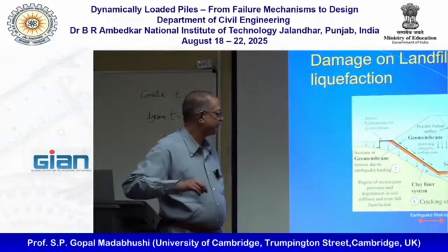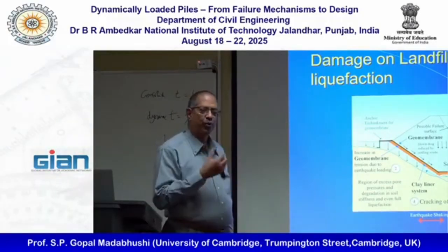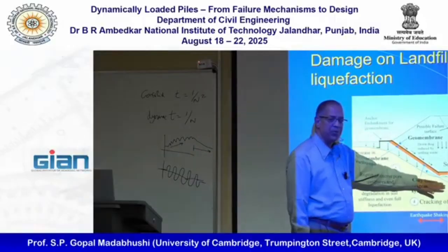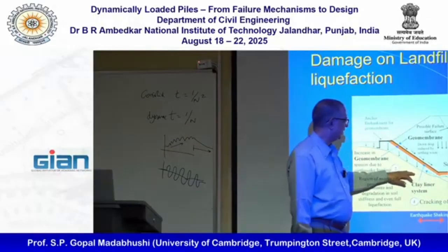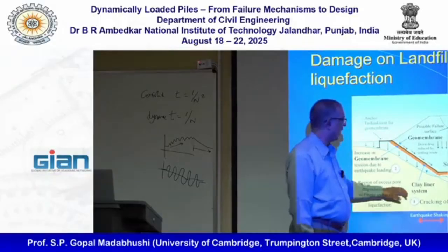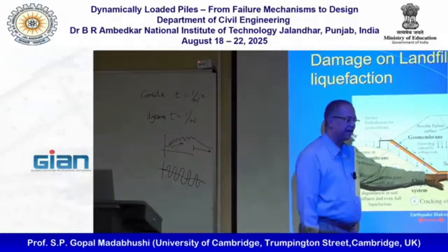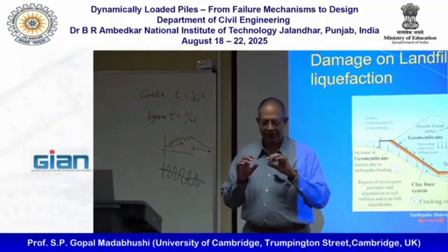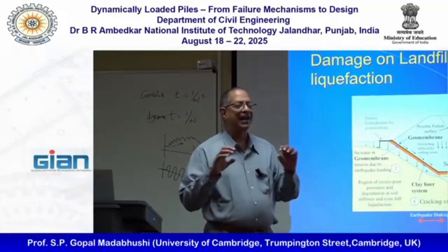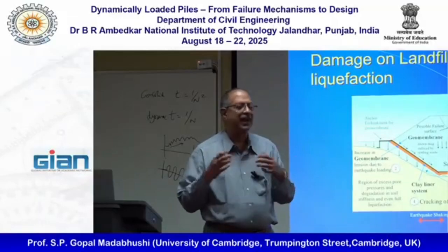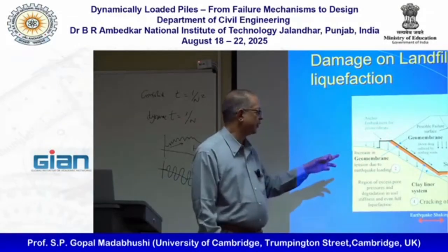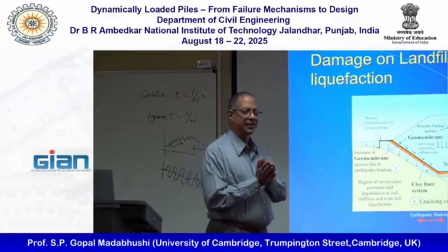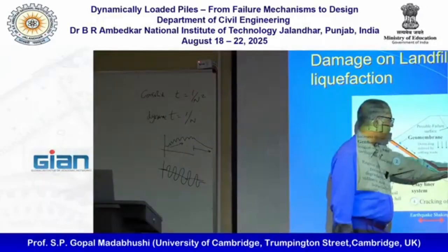Nobody has worried about this: if I have sand below and I get an earthquake, I could liquefy the soil and that can lead to uneven settlements. And these things are very sensitive to cracks. It's a clay liner, right? Clay is not great at carrying tension, so it is very easy for it to crack. Then I'm only relying on this geomembrane to hold my leachate, the horrible stuff that forms at the base of the landfill.